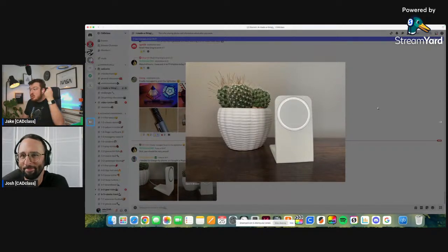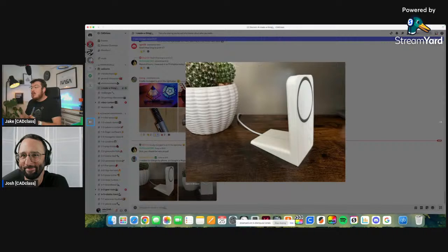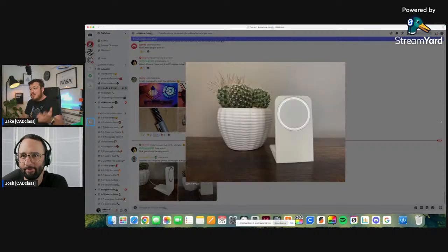It looks legitimate. And he is using the actual texture of the build plate to make it look that much more professional. If I was going to print this, I would probably print it on its side so that our layers are cutting through that L shape and it makes it that little bit stronger. But this project looks cleaner and it looks better. So hats off to you. Really good design. If you did it purposefully or you didn't, this looks brilliant.